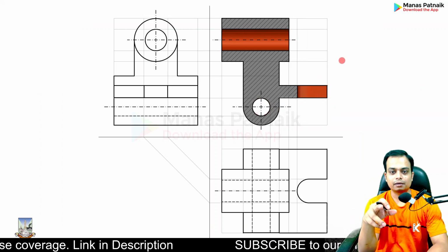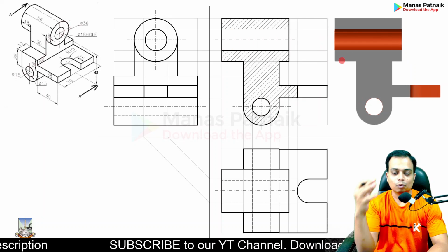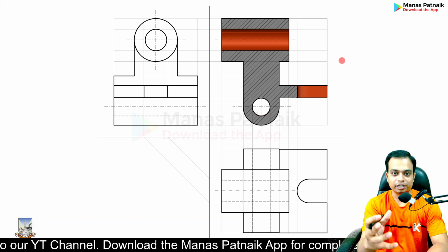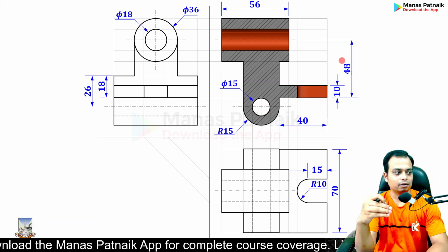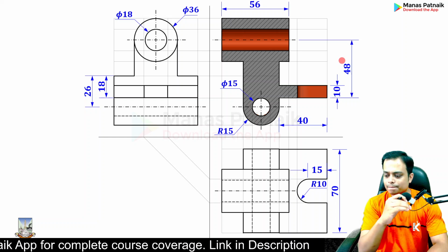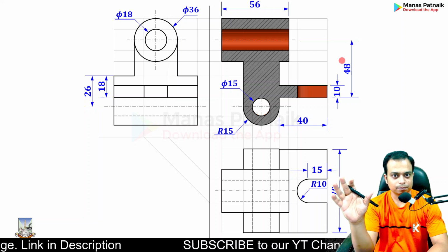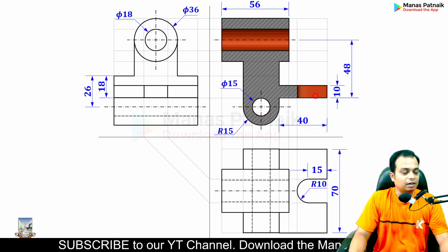This is the pic that we took from AutoCAD, and it fits in perfectly with our own created drawing. Looking good. We were also asked to show the dimensions, at least 10 dimensions. So here they are. The font size is a bit bigger so that you can look at these dimensions clearly. In examinations or whenever you are doing manual drafting, keep it between 3 to 5 millimeters, not more. As far as the font size is concerned, this is what I'm talking about. Yeah, that was the problem.